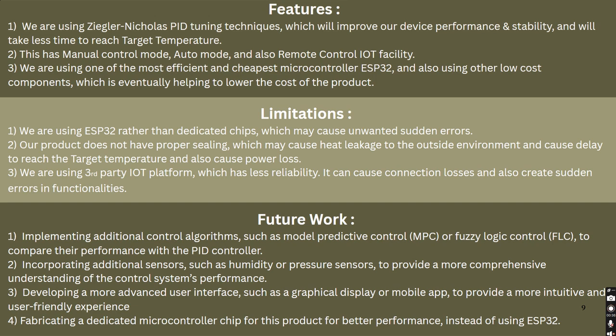Limitations. We are using ESP32 rather than dedicated chips, which may cause unwanted sudden errors. Our product does not have proper sealing, which may cause heat leakage to the outside environment and cause delay to reach the target temperature and also cause power loss. We are using a third-party IoT platform which has less reliability. It can cause connection losses and also create sudden errors in functionalities.